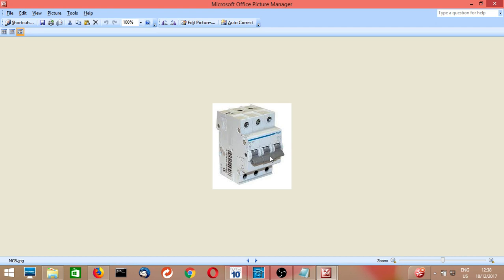The normal MCBs used for designing the starter are not in the motor protected range, because that is very high in price. So we are using a normal MCB, and we have to consider the starting current of the motor. It is 5 to 6 times the starting current of the motor.